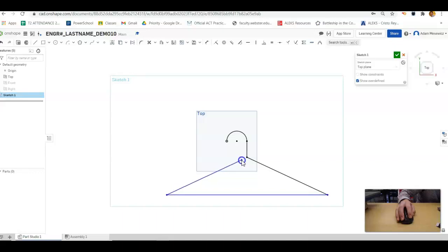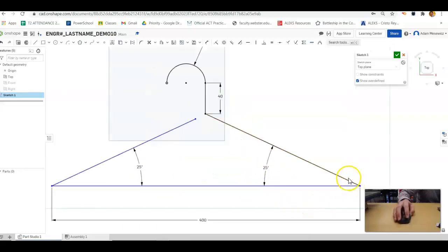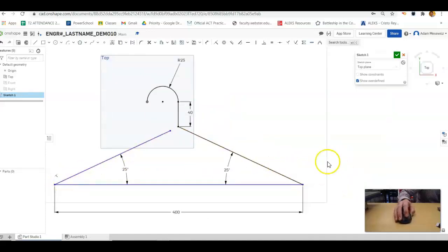So I want to click and move it pretty close to where this is going to almost intersect, but it won't touch all the way because remember, we can't use sweep if our paths intersect, okay? And so now that looks pretty good. So the only issue that we have with this hanger right now is that these sharp corners would rip your clothes. So this would not be a really effective hanger.